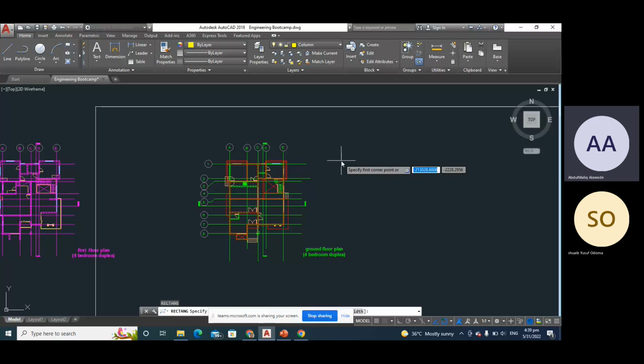So that's like an advantage, especially if you are doing high-rise buildings. Architects most often than not will have given you options on where you are going to place your column. So in that instance, you can use the size prescribed by the architect. It is a suggestion. If you run your analysis and the column size works, it's fine. But if it does not work, you have to increase it. If it is overworked, you have to reduce it.